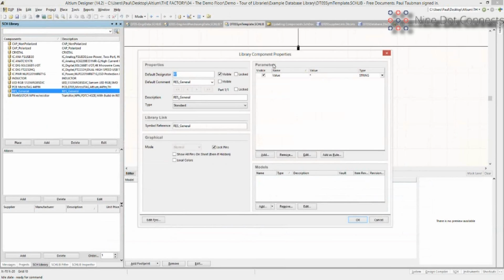Okay? I also have this thing called value and price. And wait a minute, I thought you stripped out all the values. Well, I did. The reason I left this in is just a little note for you guys who are already doing this stuff: I did this for formatting purposes. So in Altium, I turn this on, but I also said make it visible. So when I go to my libraries and I place it, the value will be superseded with the one that's already in the database, but Altium will make it visible upon placement.